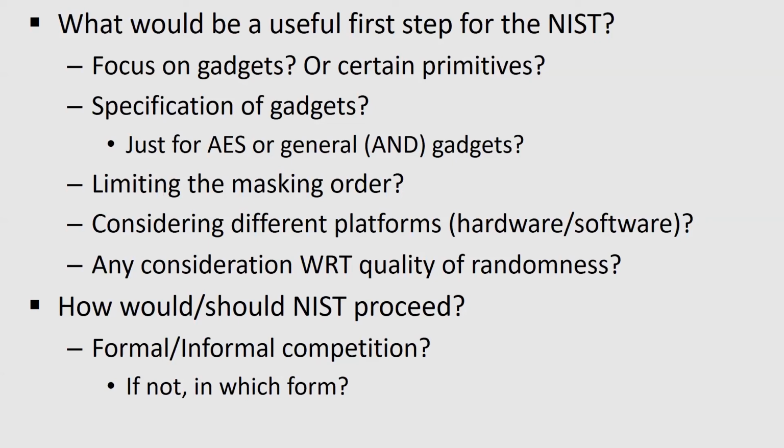Yeah, I think that the security order alone may not be the best metric, so maybe we should combine it with some type of noise estimation as well. But I also see an issue, especially for lightweight ciphers, if you want to apply those standardized gadgets. The noise level might be really low on certain platforms, so the recommended security order needs to be really high to achieve an equally distributed DPA security level throughout the statistical moment landscape. Then this doesn't become lightweight anymore, right?